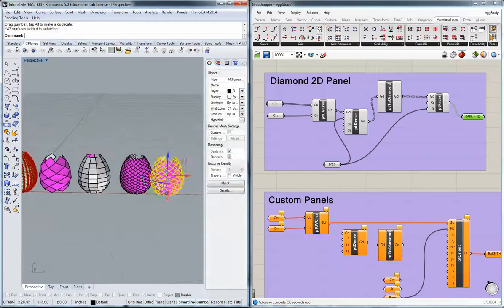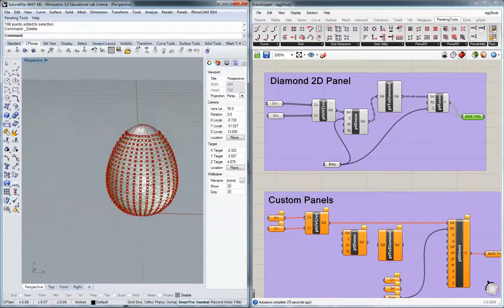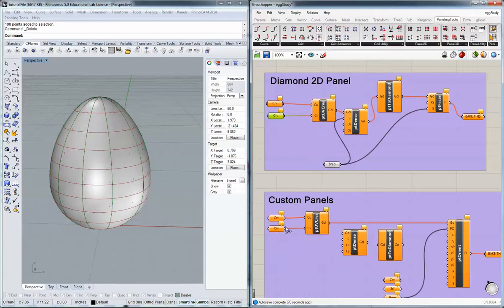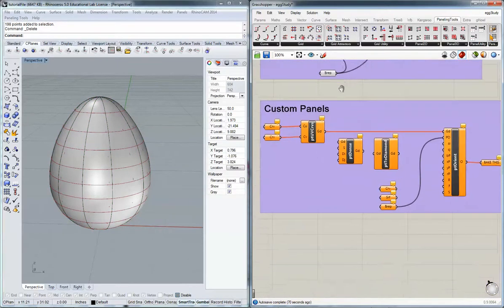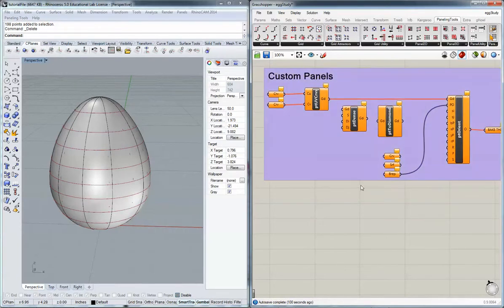Okay, so one last thing I'd like to do, and again we can go back to, I'll go ahead and clear these values to start with our original ISO curves, is looking at custom panels. Simply put, this is a way to reference a shape, a surface, a volume of some kind as the panel. Then within a given series of points, that panel can get morphed or manipulated based on where it falls in a surface. It's actually one of the more powerful tools that we have in this plugin.